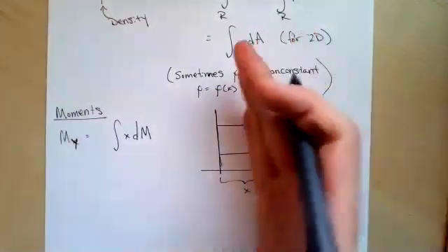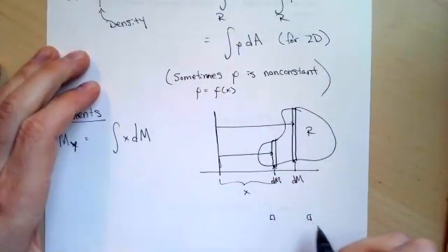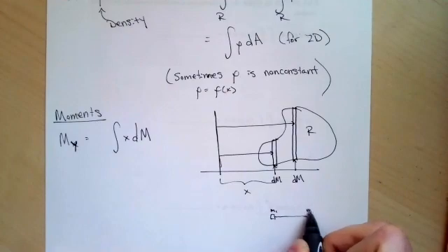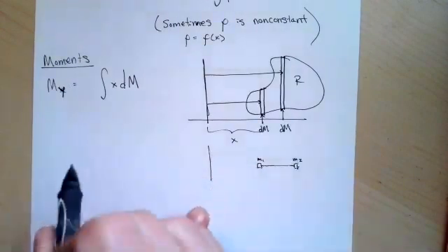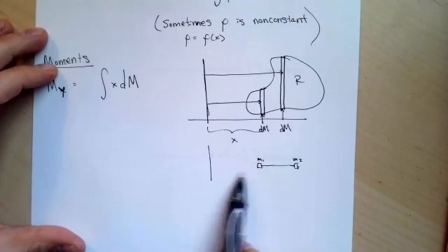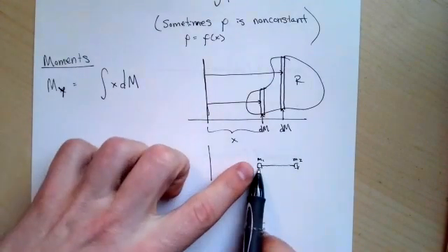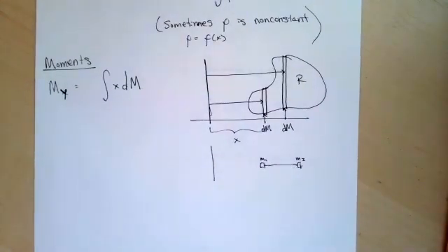So you can kind of think about it, well, if I didn't have a strict shape, if I just had blocks, right? If I had this block, and let's say they were connected by a bar that was massless, and we just had M1 and M2. If I were to rotate this bar now around the y-axis, then again, we are in some sense calculating the torque, the force times the lever arm, or the mass times the lever arm gives us the inertia. And we would just add up the individual moments of inertia for a discrete system if we had individual masses.